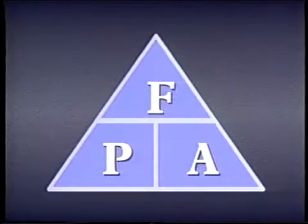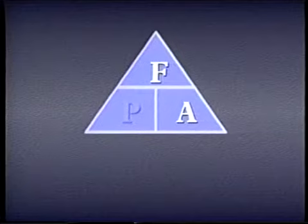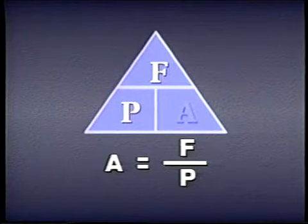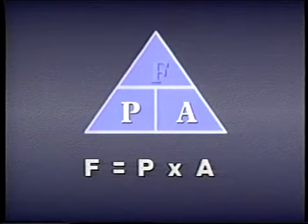Now there's an easy way to remember this formula. In this triangle, if we cover up what we are looking for, we can see the relationship with the other two. For example, if we are looking for pressure, we cover pressure, and we see that it equals force divided by area. If we are looking for what area will transmit a certain force at a certain pressure, we cover area and see that we have to divide the force by pressure. If we are looking for force, then it's pressure times area. Remember that force is at the top of the triangle.